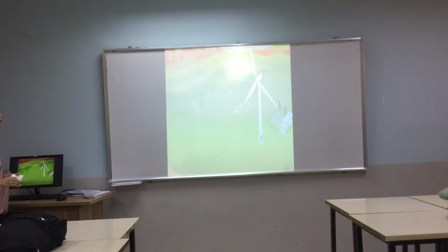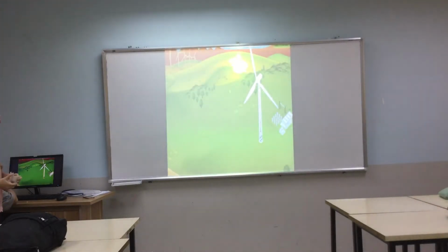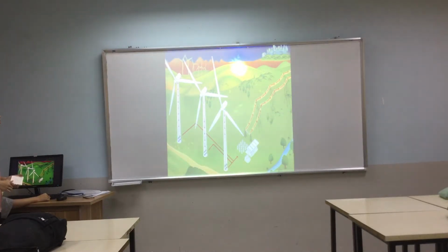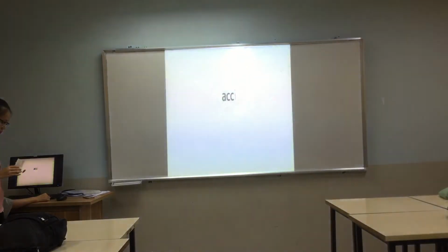The electricity produced in the generator as direct current is conducted through the interior of the tower to the base. There, a converter transforms it into alternating current, which is the most commonly used kind, and a transformer raises the voltage for transport inside the wind farm. From each turbine, alternating current is sent to the substation through underground cables. Here, the voltage is increased again to feed it into the power grid and transport it to end consumers. This is how we use the wind to light cities, feed industries, schools or hospitals, or operate our household appliances in a clean and sustainable way.